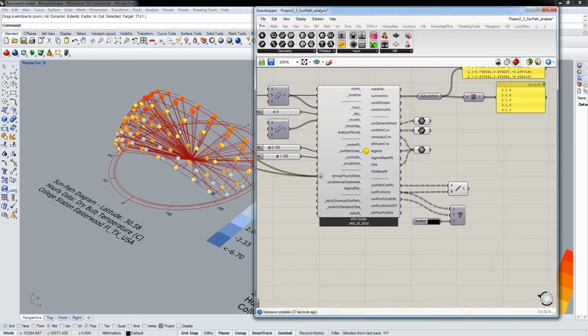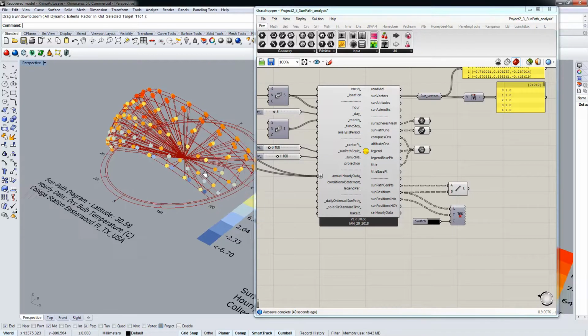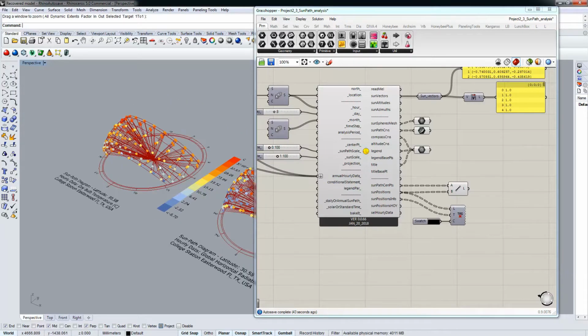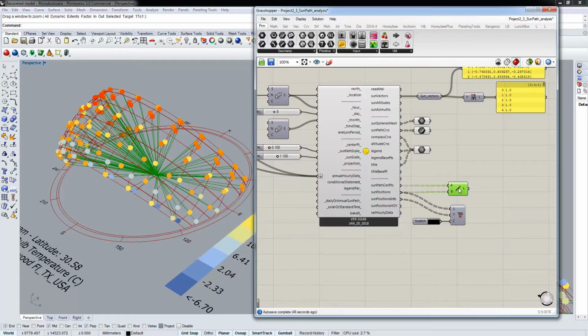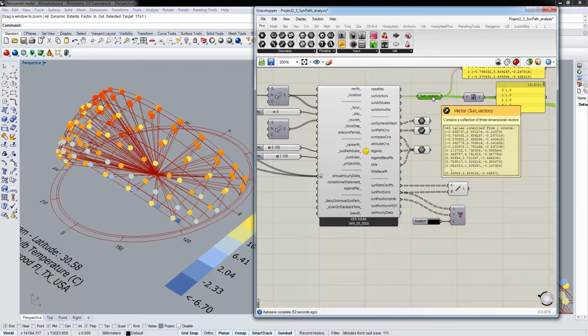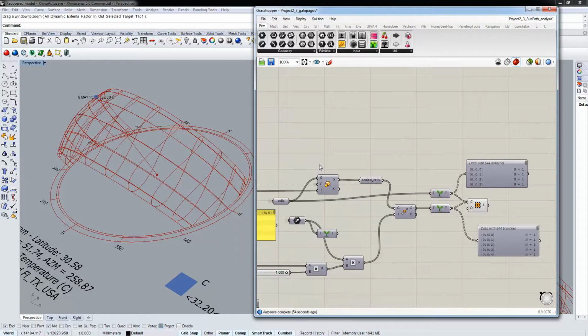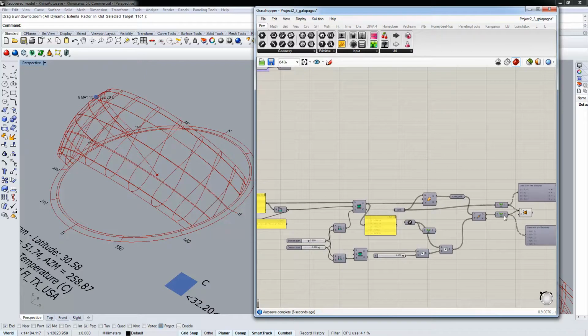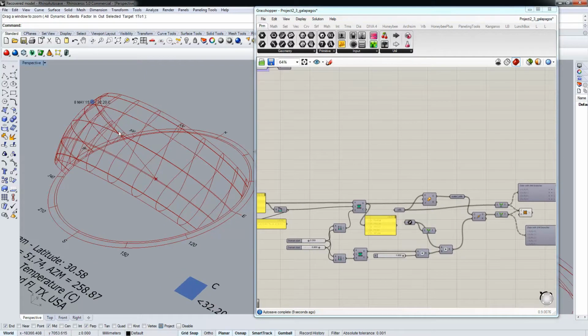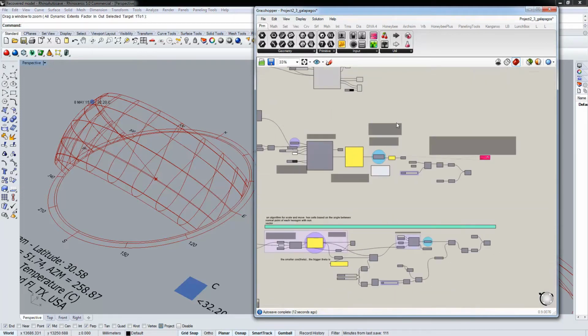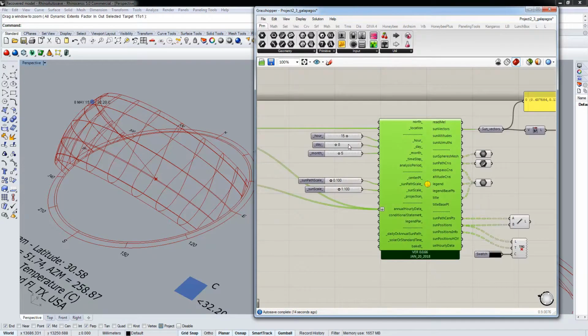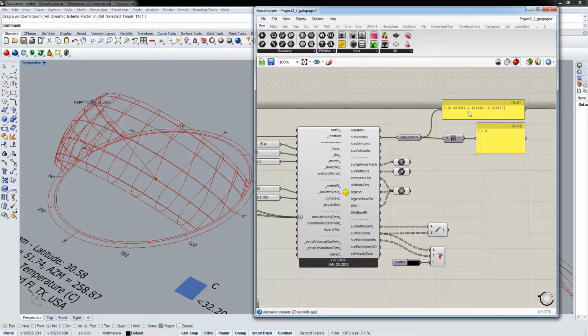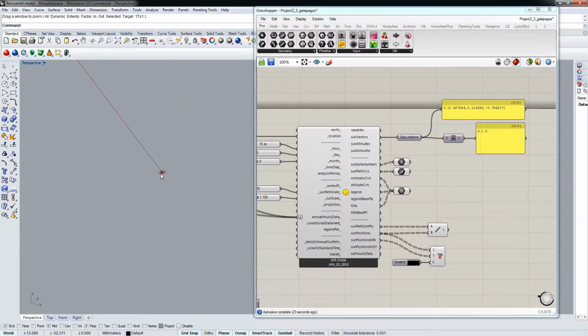And the results are shown here. For example, I get two sun paths because I chose both the dry bulb temperature and the radiation. The important thing is that you can also get this line, which is actually the sun vector between your project and the sun. For my project, I only needed to calculate one sun vector because I wanted to adjust my openings based on the sun vector, and that sun vector could change each time. So I imagined 3 p.m., 8th of May for this project, but the time can be changed with the slider and cause a different pattern each time.